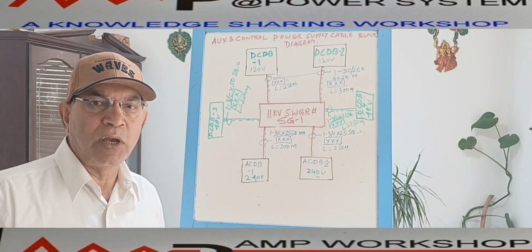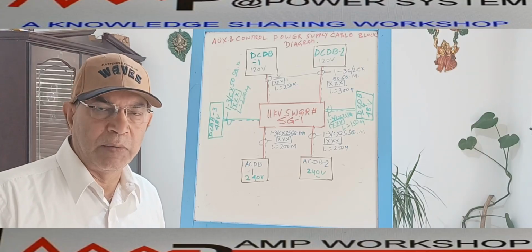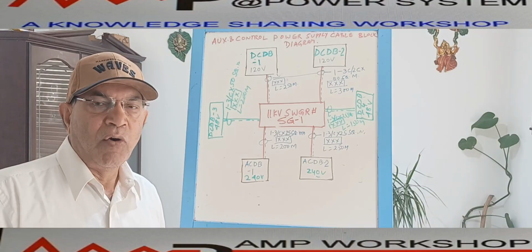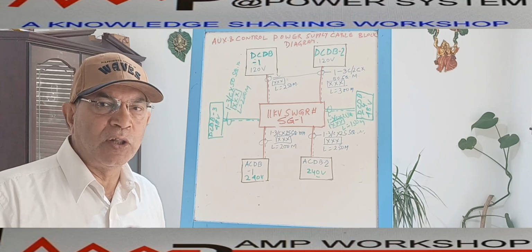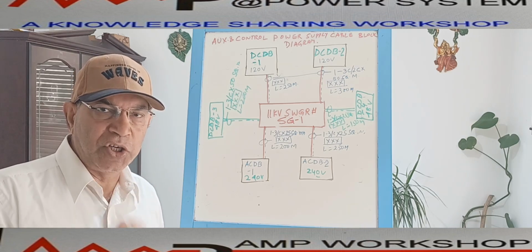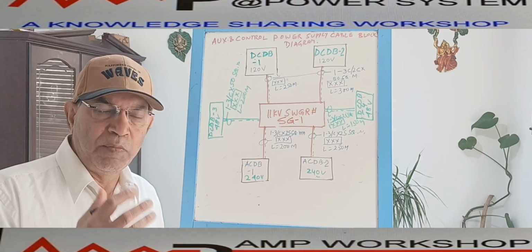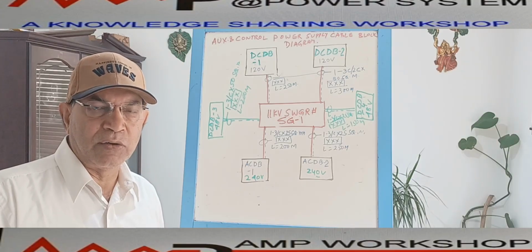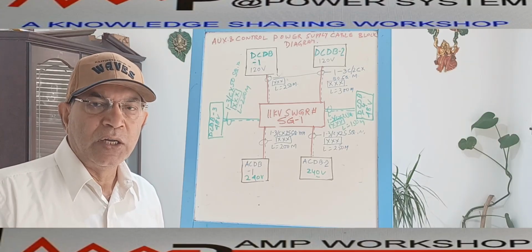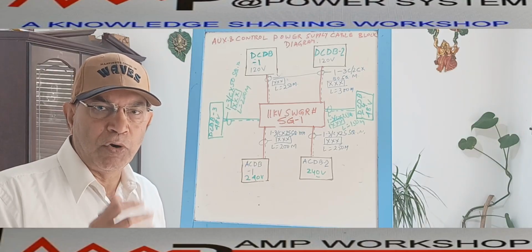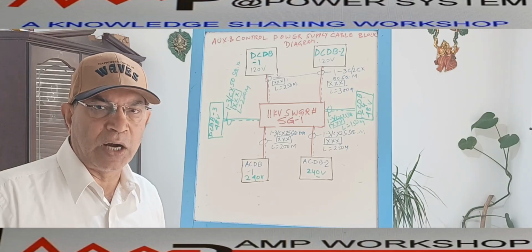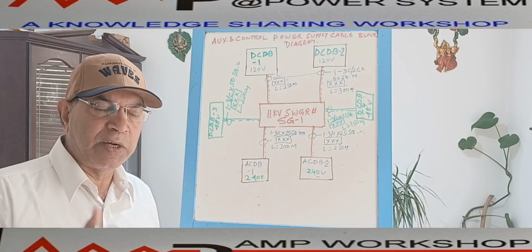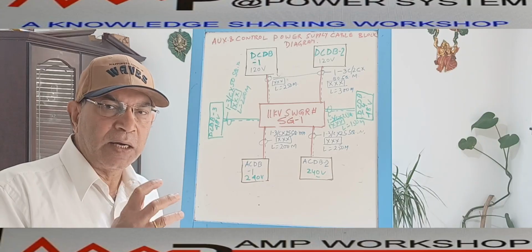In addition to this, we have already discussed during our control power cable block diagram that for the various AC motors, generators, and all the rotating machines, to keep their windings heated when the equipment is not running, there is a space heater inside the generator enclosure as well as the motor enclosure. This space heater would be on when the motor or the generator is not running. But that space heater power is coming from the switchgear panel, from the respective panel, through the breaker NC contact.